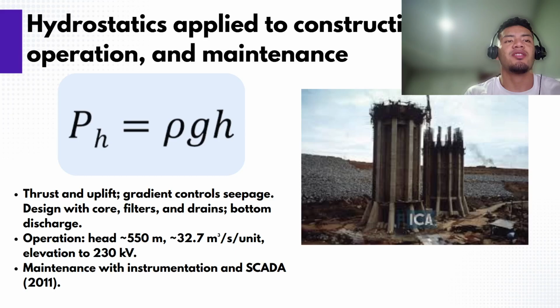Hydrostatics in construction, operation, and maintenance. Hydrostatic pressures increase with depth, creating thrust on the upstream face and uplift on the base. The hydraulic gradient controls seepage and piping in earthfill dams. In design and construction, the cores, the filters, and drains limit seepage and reduce pore pressures, and the diversion tunnel works as a bottom outlet with gates.